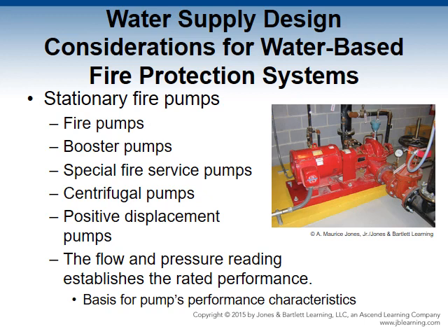Another pump is a positive displacement pump, which are more commonly found on fire apparatus. They are suited for water-based fire protection system applications, including foam, water system, and water mist systems. These pumps operate at a specific speed to deliver a predetermined pressure and constant rate of flow.